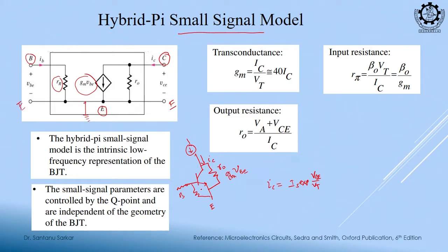You see, these resistances are not really there, we are modeling them, right. So, physically are there any resistances? Physically there is no resistance, but the current expression is like this. So, in this zone, if it is flat, this R naught has to be a high resistance, right. What is this R naught? Suppose this is Vc and this is Ic. So, what is the value of del Ic? Almost 0, right. So, this R naught will ideally be very large, agree.